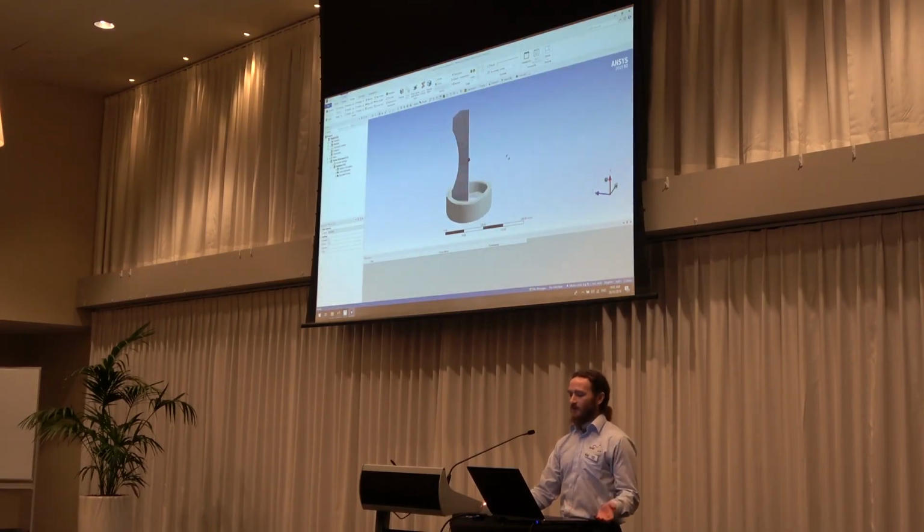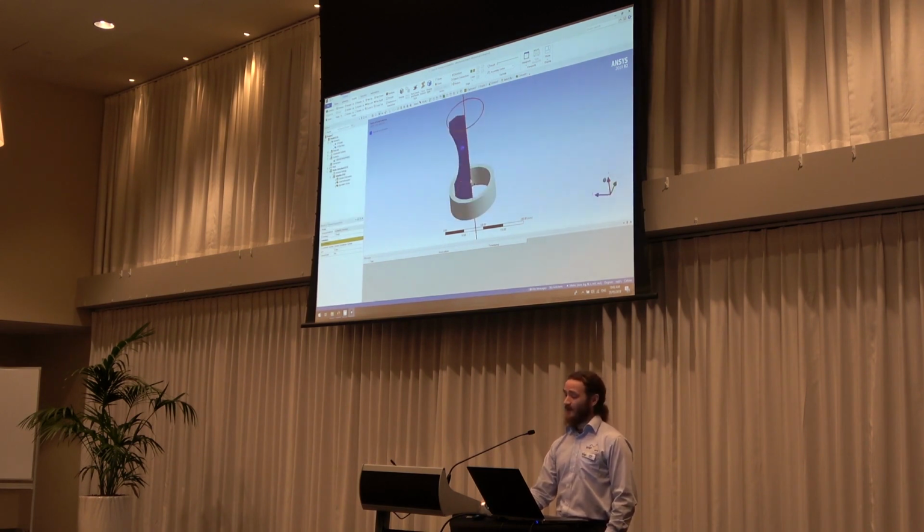So here's my 3D model. I have a 3D solid body here, and then I have a 2D axisymmetric body there. I go into symmetry, insert a general axisymmetric feature, and scope it to that body. Now I need to give it an axis of symmetry. Conveniently this lines up with the x-axis in my global coordinate system, so I don't have to worry about that. I'll give it 12 nodal planes. So you can see the nodal planes there now.